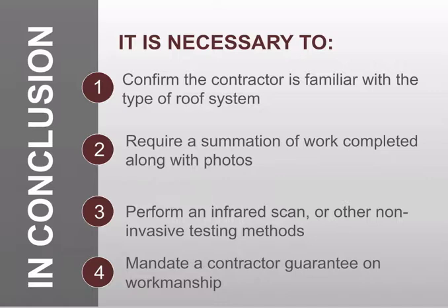So in a repair, we want to see really a minimum of like 6 months. Yep. I would say a good professional repair. Some really longer term repairs, we could expect 2 years. When we start getting into that strategic repair scenario, we want to look at 5 years. Yep. Industry standard on a roof replacement, like I said earlier in the presentation, when we see 6 months up to 2 years, really we're mandating 5 years to 10 years, because we want to make sure that we're protected through the manufacturer on the warranty, but also through the contractor on a workmanship guarantee.